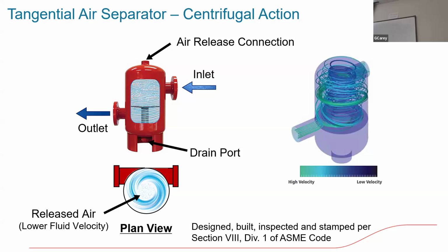And then there's a stainless steel collector tube in the middle where it's kind of slower and quieter, because that centrifugal action is taking place on the outer edges, and the air bubbles kind of gather, and then they'll typically release at the high point with some type of high capacity vent. Very efficient, been around a while, very popular in the hydronics industry. It's a good understanding of just what's going on. They'll refer to it as centrifugal action.